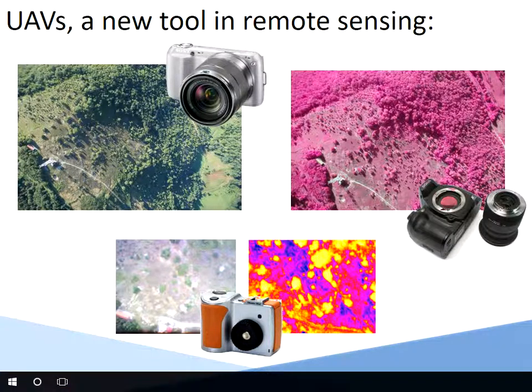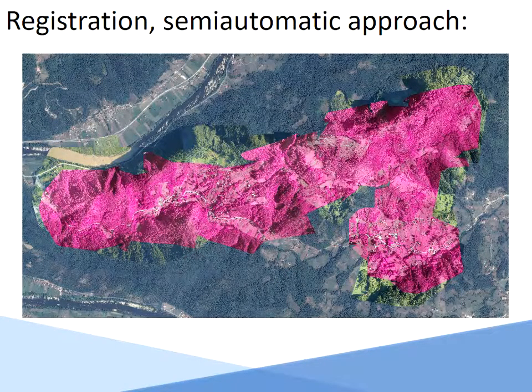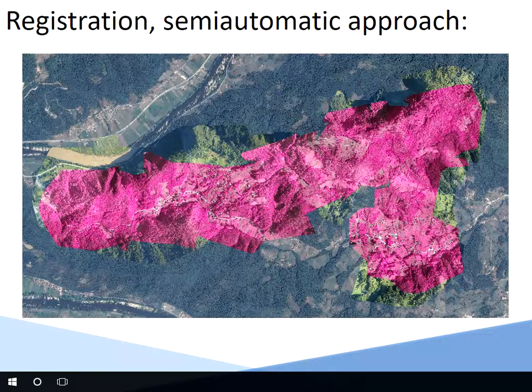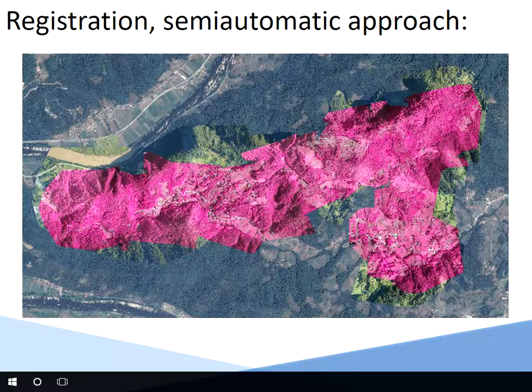So the traditional mode to do this is to retrieve the orthophoto mosaic, that is, do our flight with a certain overlap in order to, across some feature points, match all the images from each flight, and afterwards with the manual operation of the software we can add some manual points in order to co-register all the different mosaics, ending up having something like this, in which you can see the background, the reference image, and here 2 different flights done in the area, one of the near infrared, another one for the visible camera.